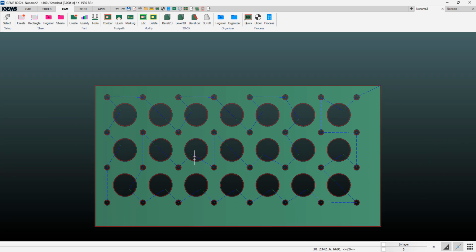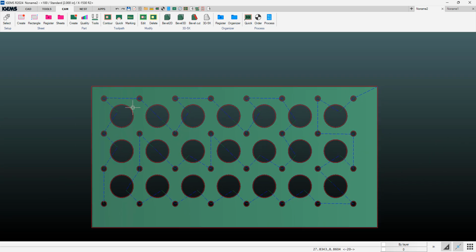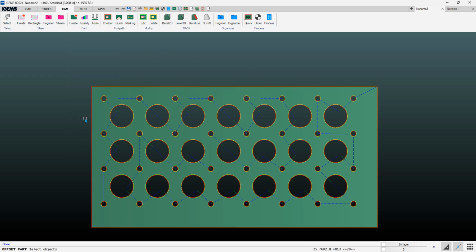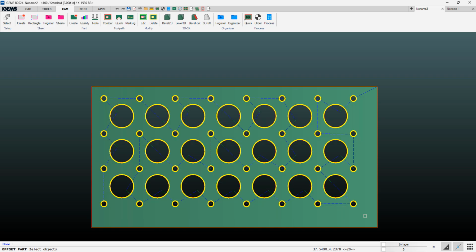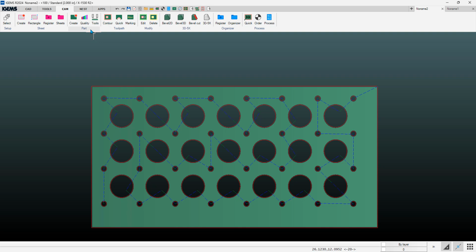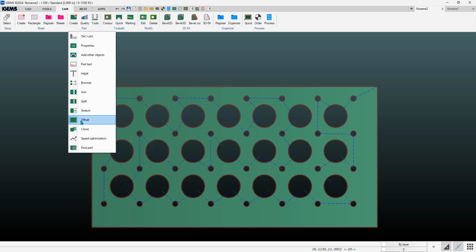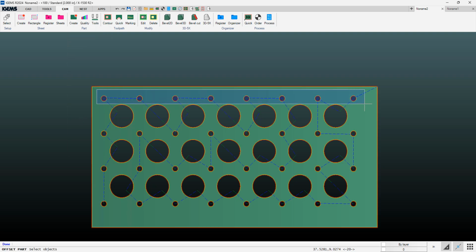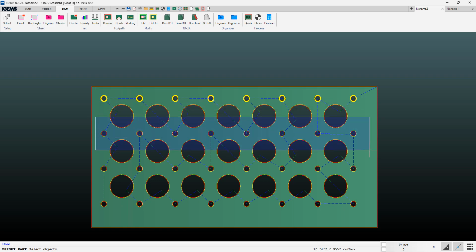Now what about in this scenario here? Maybe these larger holes are cutting close to size, and again, you only want to change the diameter on these smaller holes. We do our part and offset command. Select objects. If I do this, it'll get everything. I can do something like this. Since I'm doing a left-right box, anything that's within the box it'll select.